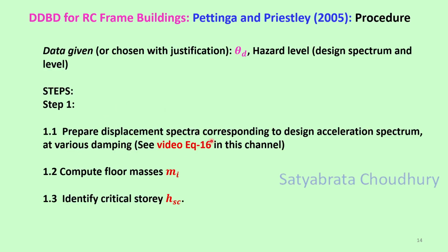1.1, prepare displacement spectra corresponding to the design acceleration spectrum at various damping. You can see video number EQ16 in this YouTube channel. The conversion is not very hard. You can do it in an Excel sheet. You only have to use that formula.